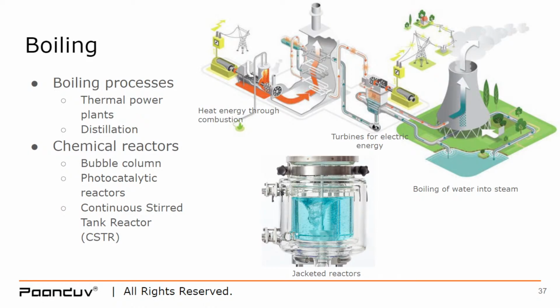So when this conversion of water to steam happens, a lot of boiling and bubble formation happens, and capturing that bubble dynamics is important for the effective conversion of water to steam, to maintain the structural integrity of your system, to understand how much mixing. Sometimes you want to reduce mixing, sometimes you want to enhance mixing. So what level of mixing is going on, and there are many things that are associated with bubble dynamics. That's a whole big field of computational fluid dynamics in itself.